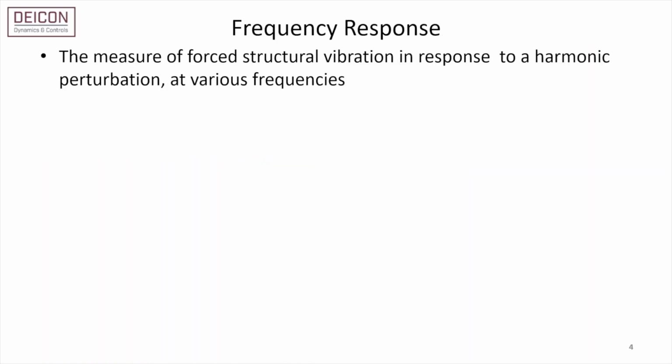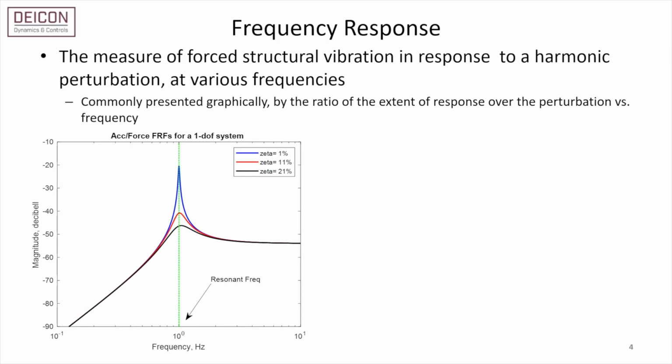The frequency response of a structure describes its reaction or behavior when subjected to periodic perturbations at various frequencies. It essentially outlines how the structure vibrates in response to harmonic inputs at different frequencies. Typically presented by a graph, the frequency response curve showcases the structure's sensitivity to different frequencies, indicating which frequencies it amplifies, attenuates, or maintains unchanged.